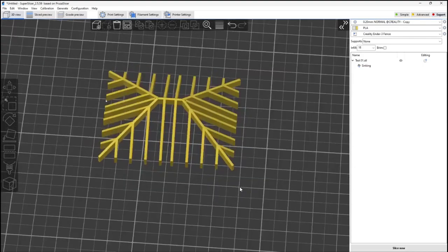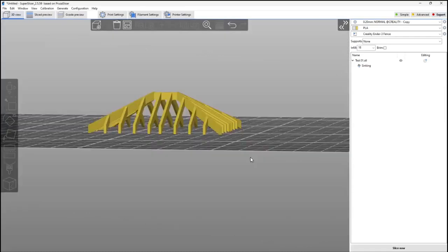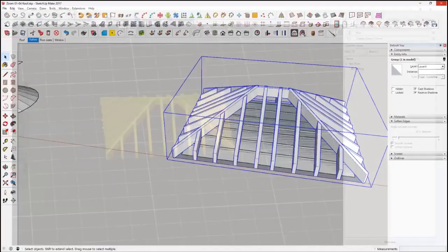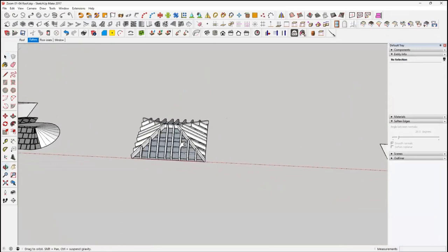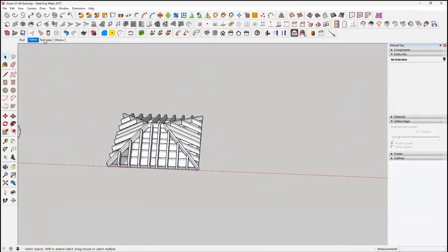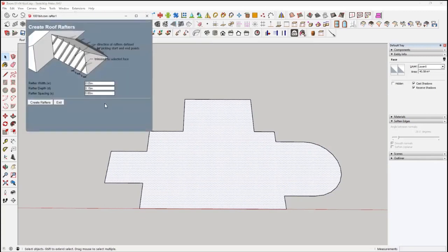So you could put that as a work in progress on your model. Take some of these rafters out, have someone roofing a building. It's quite doable. So that's your roof and your tiles, your rafters and your purlins, floor joists. Now, it's another thing. We click on the face and come along top on the 1001 bit, create rafters, floor joists on selected faces. So we click on, and there's not much here. It will do the rafters on a roof, but it will just do the rafters. It won't join it up, make a good job of it. Just the rafters going up and down.